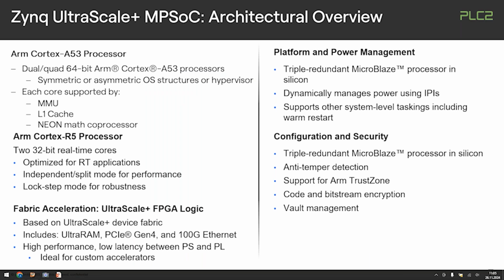Just as a summary again, one distinct thing within the Zynq Ultrascale is that you have the A53 processors, up to 4 of those working as a cluster. So you can easily have a symmetric multiprocessing Linux system with this. And basically you also have the R5 processors, not only 1, but 2 of those. The main difference of these elements is really what you want to deal with from a software perspective. Do you really want to have a low latency access into the system, or do you want to have a completely coherent processing level for your applications?